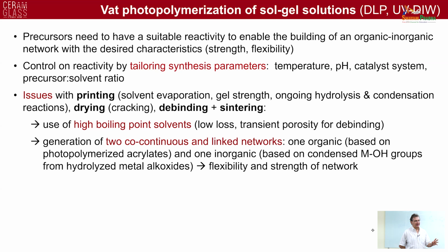You have capillary tensions, and if you evaporate the liquid trapped inside the porosity, the capillary forces drag the walls of the pores together, and this leads to cracking. So you need to control drying in a very effective way.